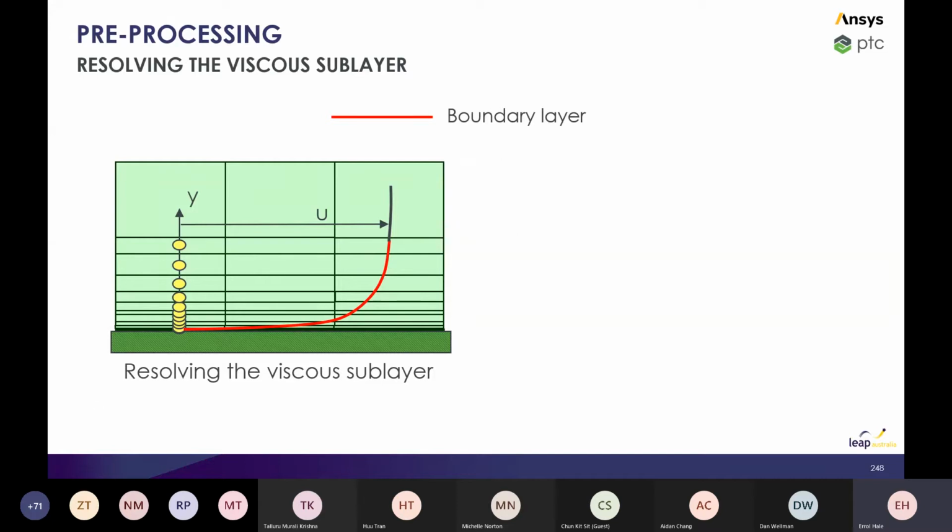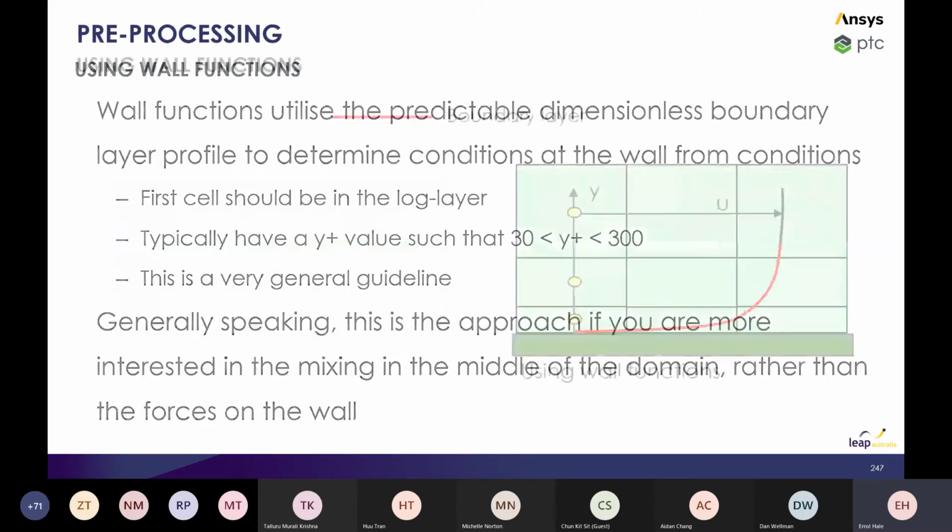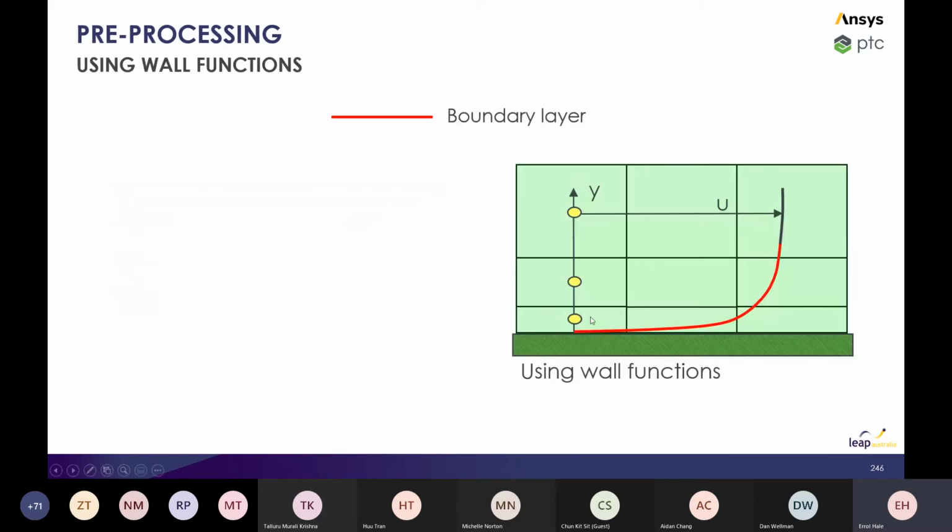Now, the important thing with both of these is getting the Y+ value right. Y1 is our first layer height, our first inflation layer. So this is our Y1 height. It's important to understand where that is in the critical regions. So the critical region would be on the front wing, in the other case where it's likely to separate, or just before.